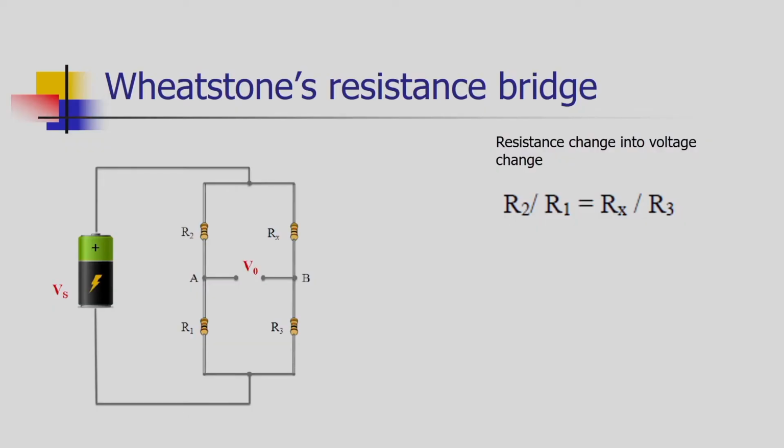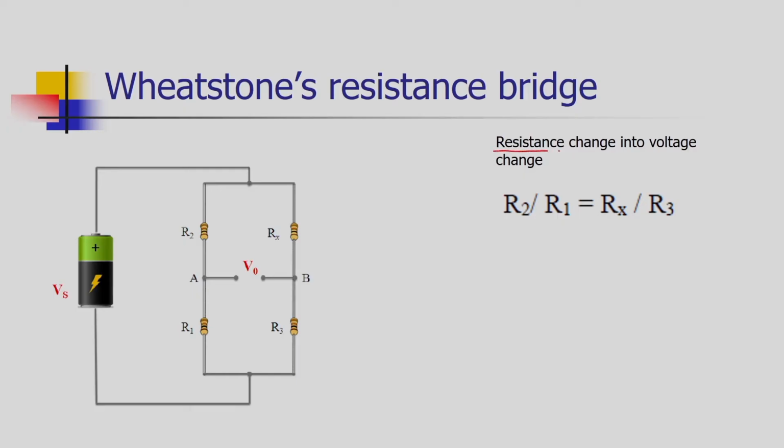Well, strain gauge element is providing us the passive output. So, passive output, as we have seen, it is producing the change in resistance. But for microprocessor processing, we need the active element, we need the voltage, change in voltage, a pulse of voltage, that is the digital signal that is useful for the microprocessor. So, for that purpose we have to convert the resistance change into voltage change. To carry out this operation we are using Wheatstone's resistance bridge.